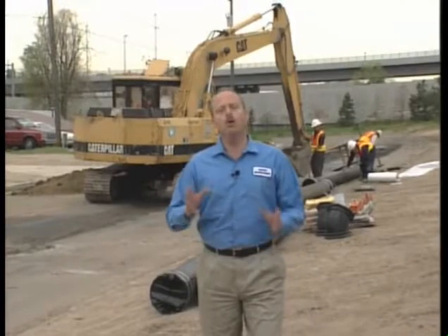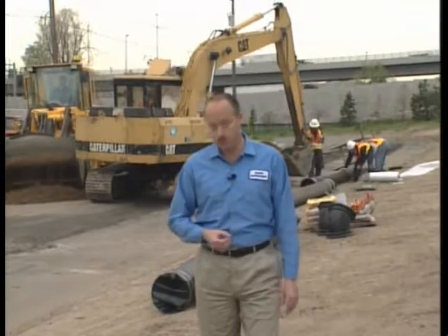There are many powerful pumps in a water treatment plant and throughout our distribution system. What happens when it's time to repair these machines or when we want to add new parts to the system? Before we do anything else, we need to make sure the water has been turned off or reduced to a safe working level. That's accomplished by carefully following lockout-tagout safety procedures.